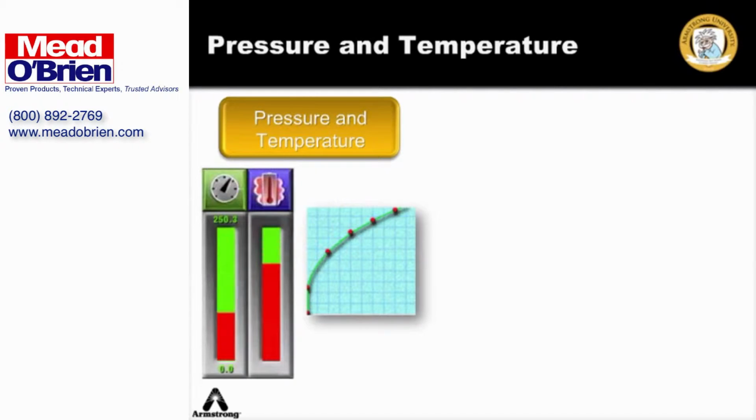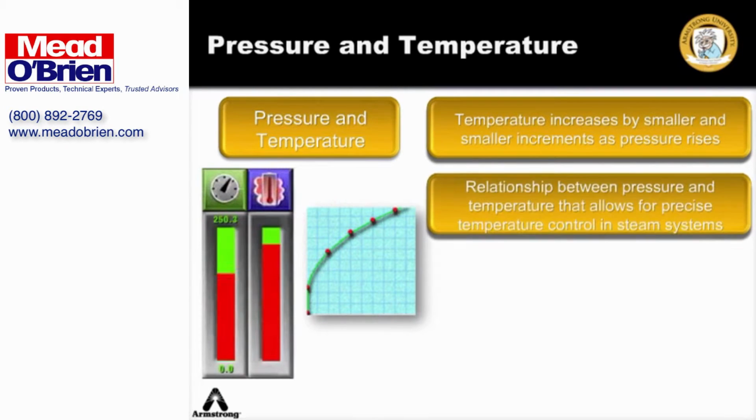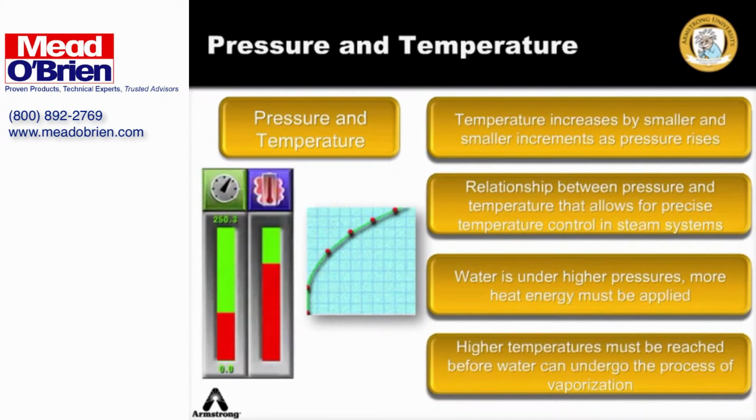As steam pressure increases, so does the temperature, but by smaller and smaller increments as the pressure rises. There is a corresponding temperature for saturated steam for any given pressure. It is this fixed relationship between pressure and temperature that allows for precise temperature control in steam systems. Rising pressure in the system has an inhibiting effect on molecular movement. When water is subjected to higher pressures, more heat energy must be applied, and therefore higher temperatures must be reached before it can undergo the process of vaporization.